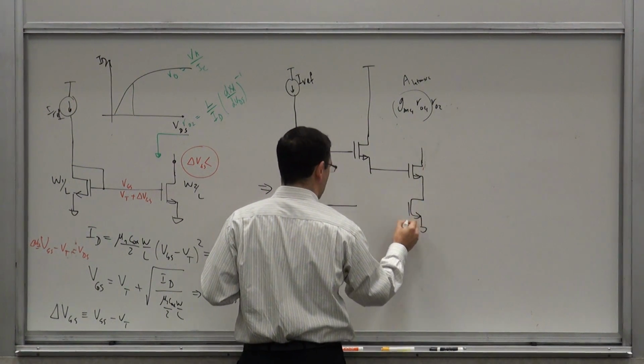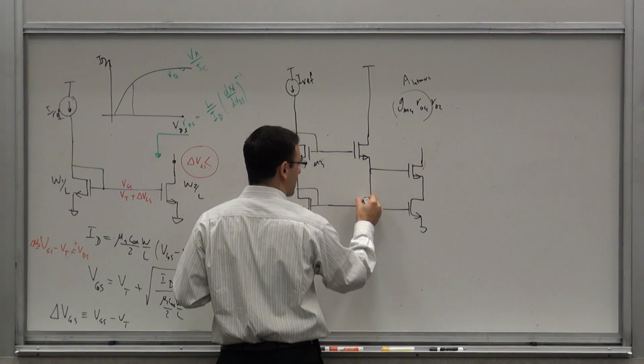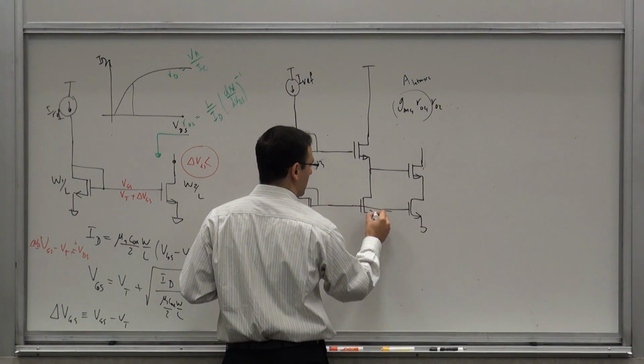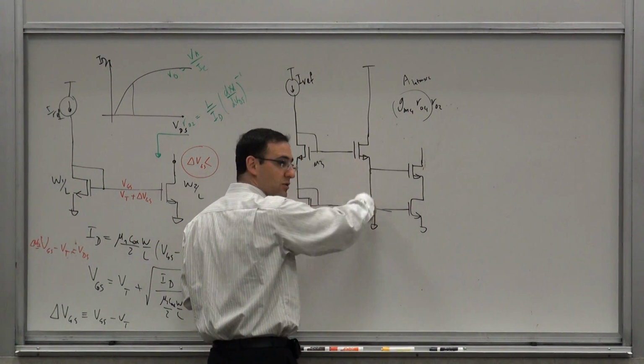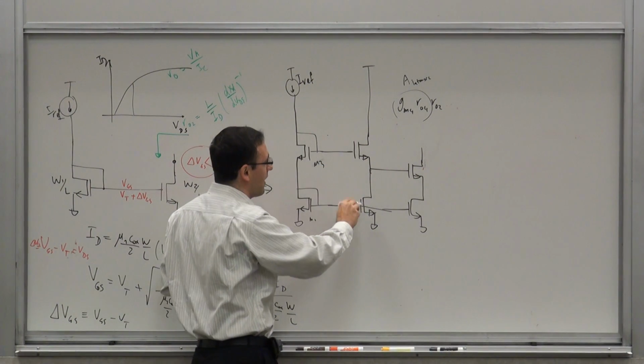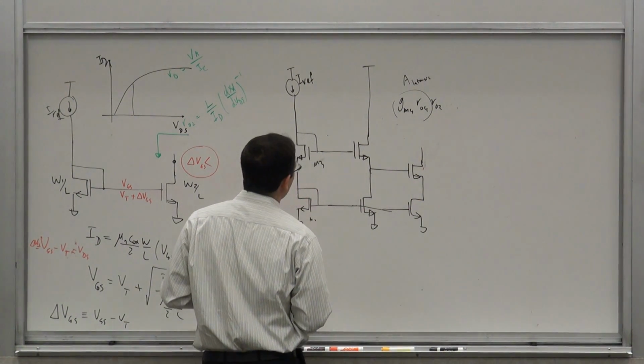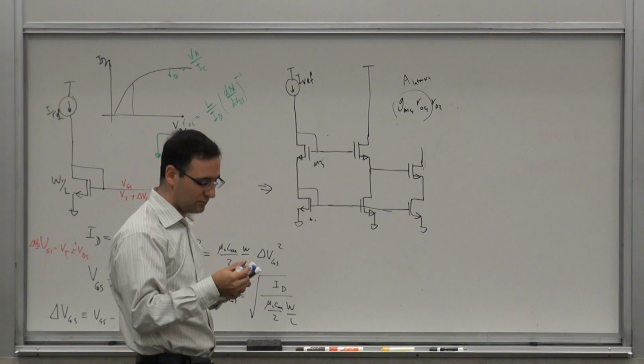And this is the lower transistor. And of course, this needs to be biased with something, so I put another current source on my current mirror chain. So you can see this is a current source, basically, created. And it goes like that. So let's see if this does solve the problem.